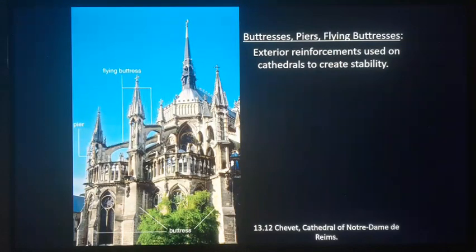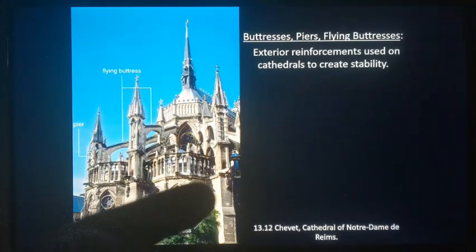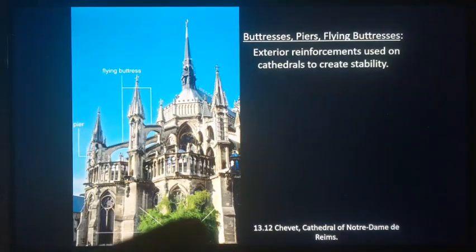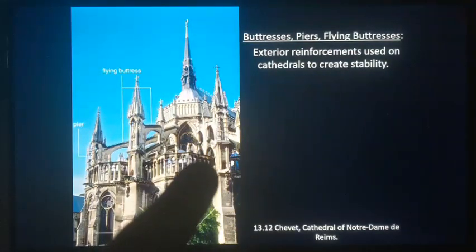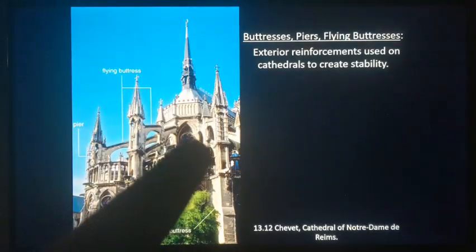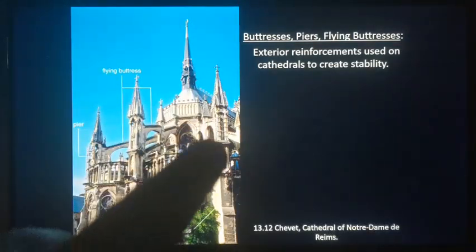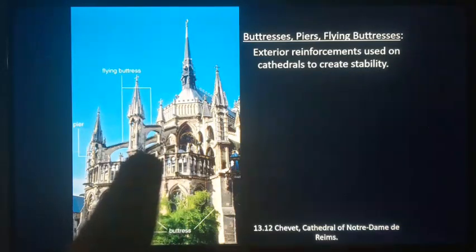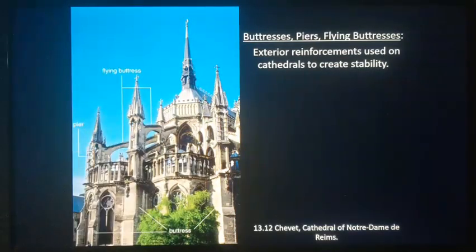So instead of like the Romanesque cathedrals just having a massive buttress at the base to support those walls from collapsing outward, instead you would have flying buttresses using these piers, which have then arches constructed to make a bridge and support those walls from the outside. So you could build a lot higher due to having this increased support on the outside of the building as well.